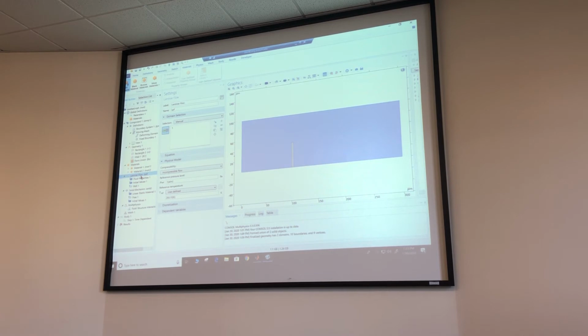So for the material one, what is the problem? Oh, is that the dynamic viscosity? Yeah, that should be 1e negative 3. Oh, see, mine doesn't even show that. This is strange because it'll show from here through 202 and I have those properties in there. Oh, wait a minute. You're having the same problem that he's having there. If you can select the laminar flow, you will select the material 2.1. Oh, it should be 1. Yeah, that's the one that should be. Yeah, exactly.